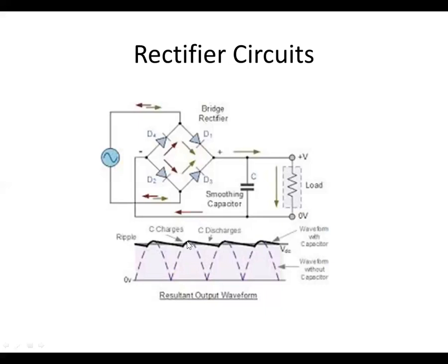And then the next cycle comes in, and then it discharges. And this is why we use the diode bridge to take that AC and convert it to pulse DC. If we only used one diode, we'd have this pulse, this one would be blocked, and then this pulse, and that means the discharge time would be much greater, and it wouldn't have as good a regulating capability for the voltage.